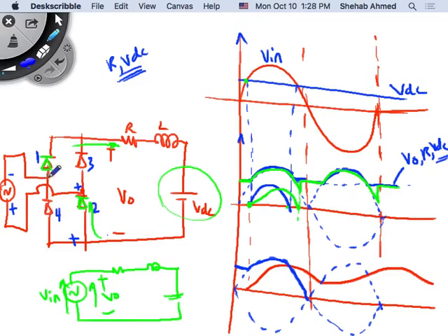4, this is a negative voltage, and this is a positive voltage, because I flipped the output polarity. So 4 will like to conduct. It's easier to conduct 4 than try to push 2 to continue to conduct. So 3 and 4 will automatically pick up as soon as V output tries to go negative. So we get something that looks like this, and so on and so forth. Okay? Any questions on this?